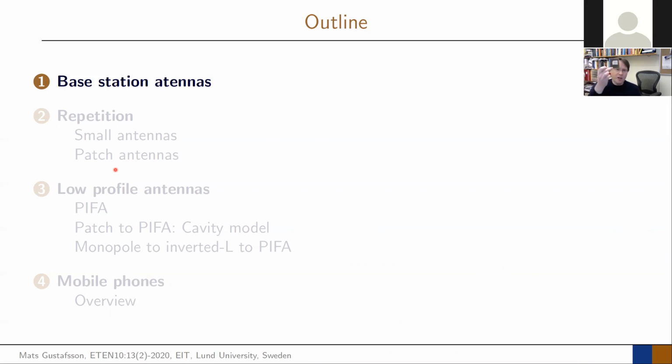So for example, this antenna you have built. And one thing we can see is that for a typical cellular phone, it's too big. So we will look at the version of a patch that typically is found in these kinds of devices, or at least was found in them. Now it's changing a little bit the last couple of years, but PIFA antennas, which stands for planar inverted F antenna, are very popular antennas in constrained environments. So you can miniaturize your patch antenna, and you typically go to what's called PIFA. So we will look at that one.